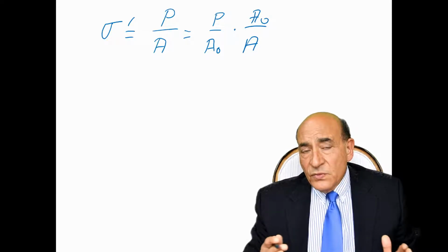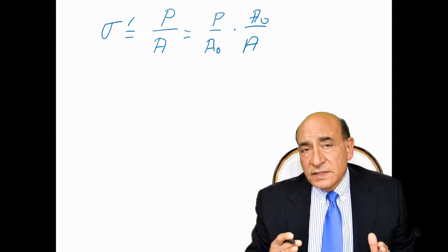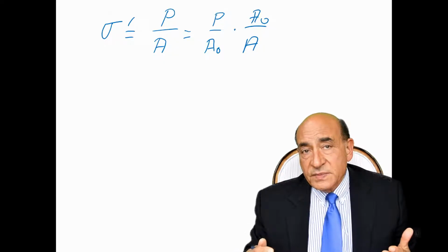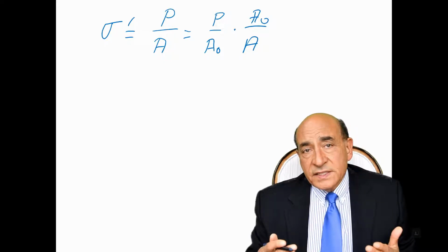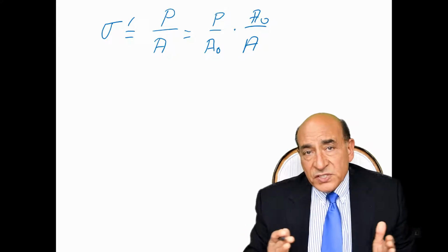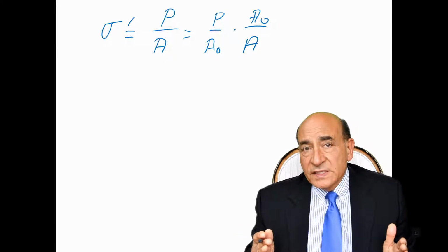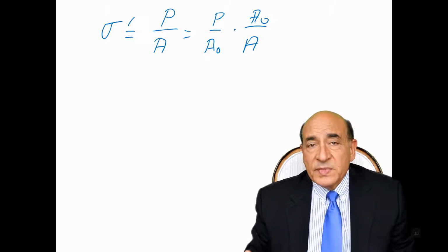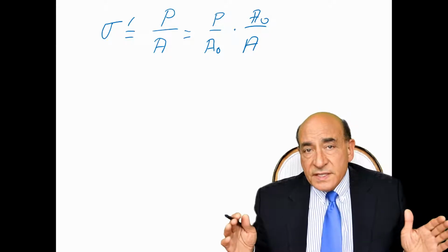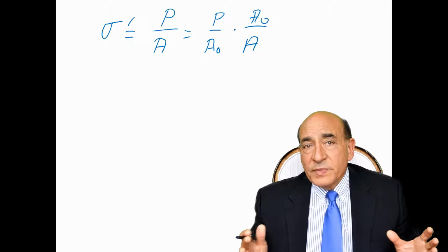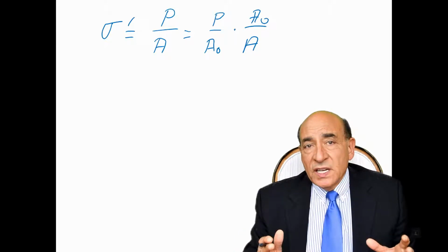Because the deformation is plastic, it is dominated by shear, and shear does not change the volume of the material. However, elastic deformation changes the volume of the material. We know that each material has compressibility, which determines how much the material shrinks if you push it hard, and if you let go, it will rebound back, but there is a small change.